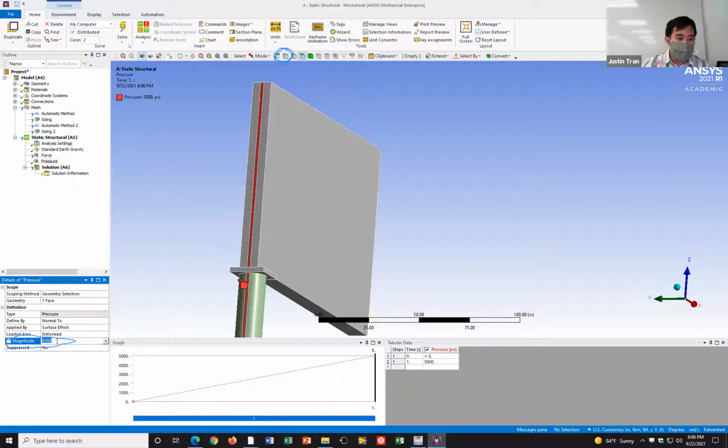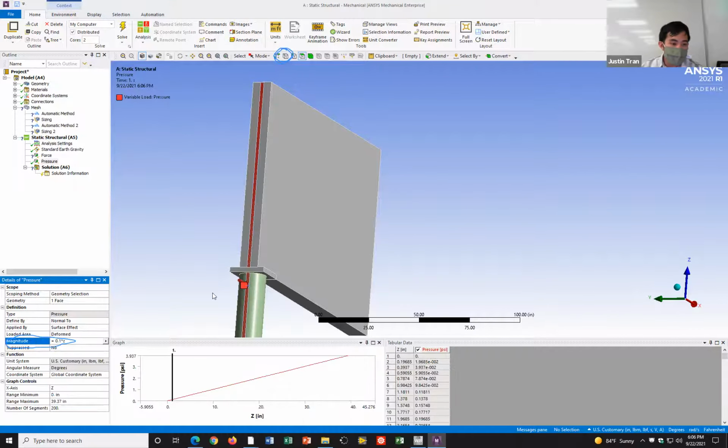To input a function, you do this basically the same way you do in Excel. You hit an equal sign, which denotes that your load is going to be a function. The function we're going to input is a very simple one: 0.1 times z. That says the pressure we apply depends on the z coordinate, or the height of where we are on the signpost. Our modifier there is 0.1. Then you can hit enter once you're done.